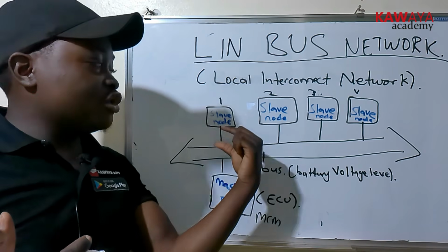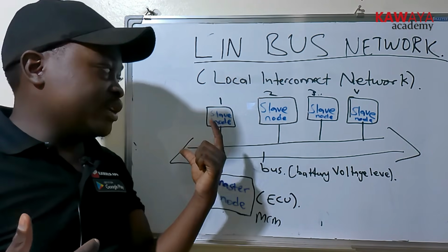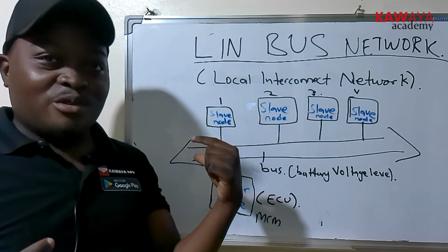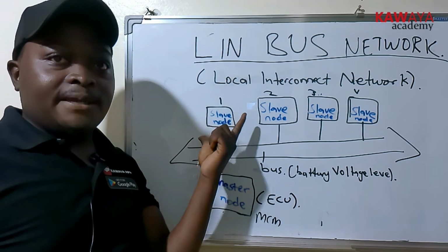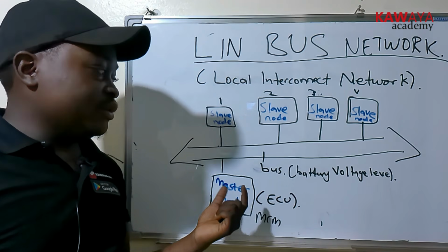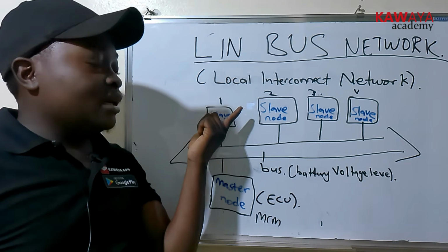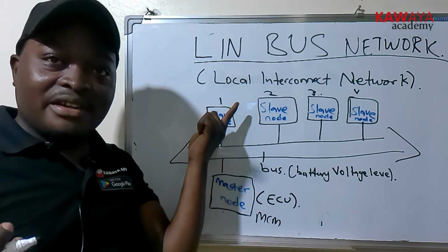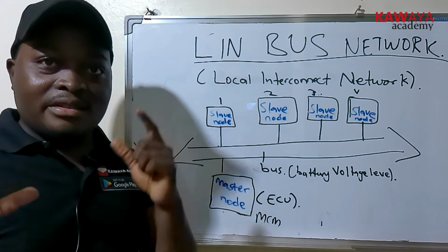The motor in the mirror is already grounded. When I talk about the mirror, I'm talking about the system which includes the motor. If you press the button and a 12 volt reference is sent to the motor, it will react by either closing, raising, or lowering the mirror.